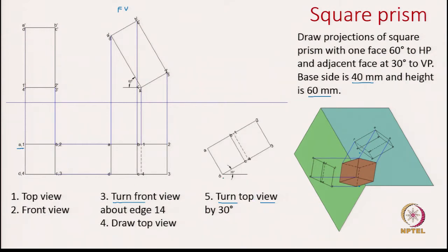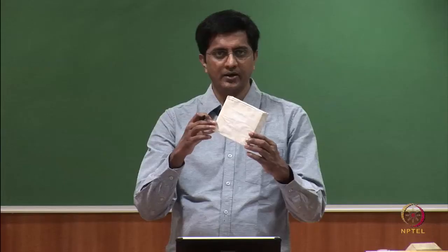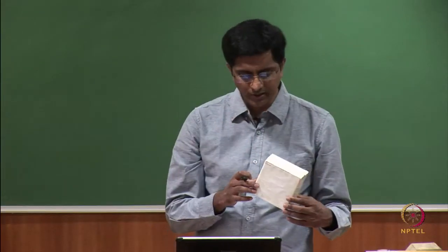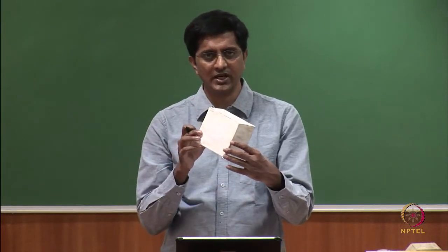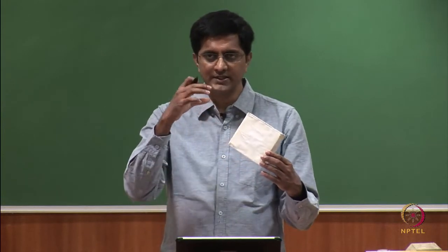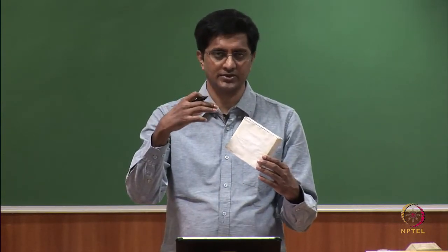So, this is the angle 30 degrees which is given, and what I am simply doing is trying to copy the top view from step 2 as a top view in step 3. The only difference is I just need to make sure that this is rotated by an angle of 30 degrees. Okay.